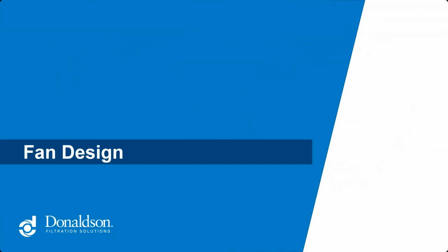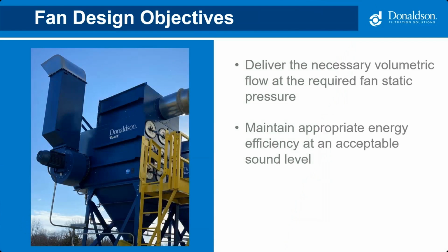All right, so moving on to the last system component, or one of the last system components, the fan. Let me explain how we size and choose a fan. So the fan has two main job responsibilities. First, it must deliver the necessary volumetric flow at the required static pressure to drive operation of the system. And since many of the dust collectors can operate with clean or dirty filters, the required airflow must be maintained over a range of static pressures, whether the filters are clean or they're dirty.